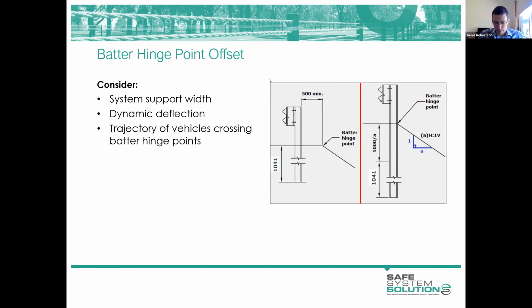Yeah, no, and the same challenges are presented in Victoria. On some lower class roads, B and C roads in particular, 2-lane, 2-way roads that have some significant volumes, but they're within fairly narrow road reserves. There's lots of vegetation. You can't widen by very much at all. And the result there has generally been to provide a wide centre line of 1 metre, even narrower, and without barriers. And it's often the case that we haven't got 3 metres to our barriers, but where that's the case, we've provided refuge bays at regular intervals.